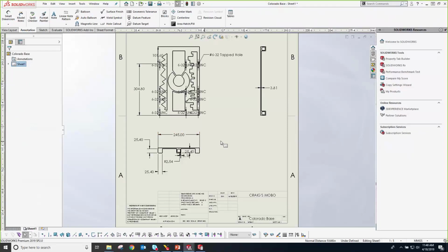So again, that's also having the benefit of having a fully defined sketch. If it's a fully defined sketch and I insert my model items, all of the necessary dimensions in order to make my part are going to be populated into my drawing for me. So that's how we can make a lot of our views or drawings a lot more quickly and save a lot of time, right? I can already have these views set up. Again, you're going to have to work with something that you're going to use. If I already had this defined as my top, right, and left, but I never actually used my front, top, and left, I would have to change these views to work with the models that I'm more or less pre-populated in the right orientation, and this would work a lot easier.